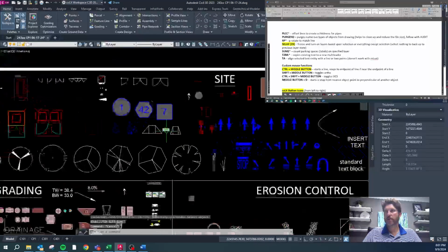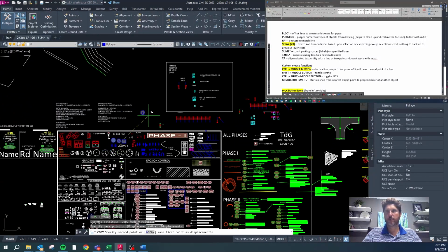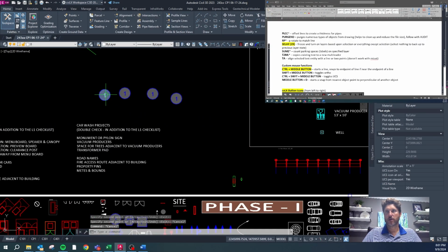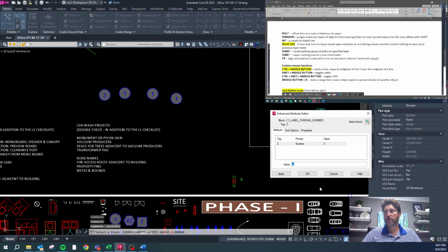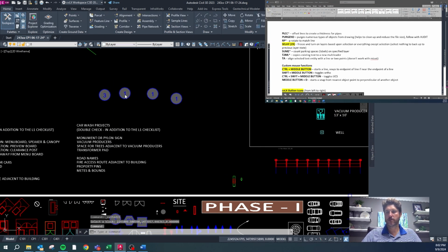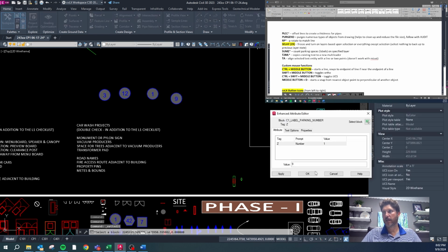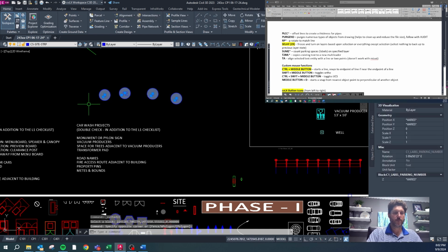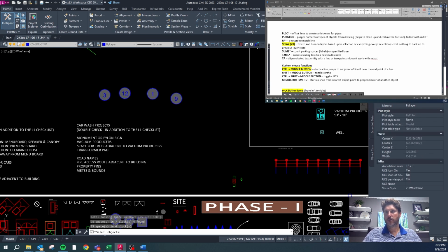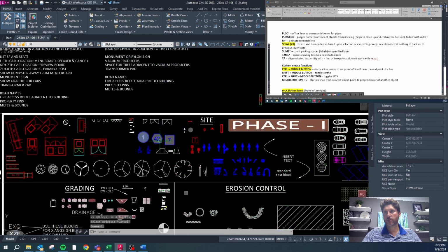SumZ counts up these parking space numbers. So you double click on it, 3 for this row of parking spaces, 12 for that row, and maybe 9 for that row. Select them, SumZ, that's the layer, hit enter, and you can see it says I have 4 blocks. I have 25 spaces in 4 blocks, but it also counted 75 spaces total in 7 blocks in the drawing, and which are probably those right there.